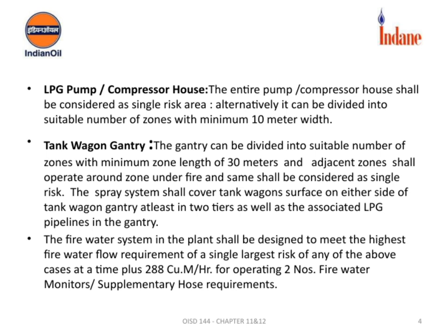Each zone should be at least 30 meters long, and importantly, zones that are adjacent and operate near each other are treated as a single risk if they are around the same fire zone. This approach helps in effective fire protection and response planning. The spray system installed on the gantry is designed to cover the surface of the tank wagons on both sides, ensuring protection in at least 2 tiers of spray coverage. It also covers the LPG pipelines within the gantry, which are critical areas in case of a fire.